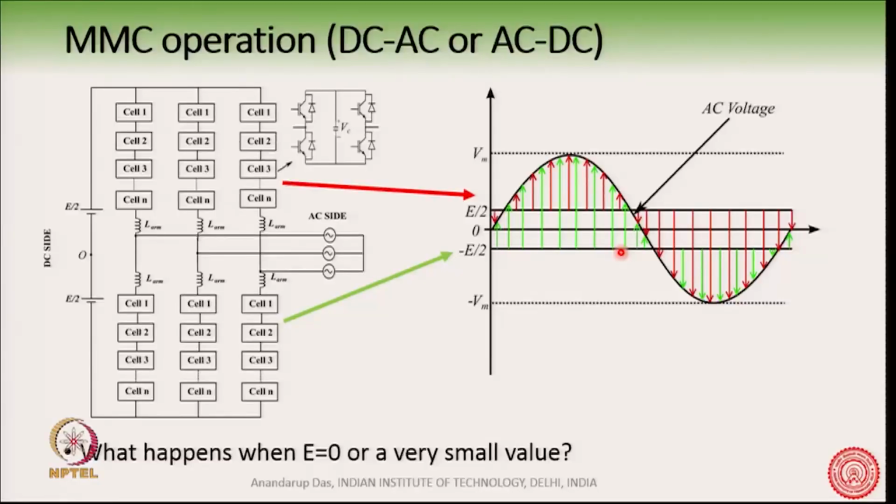The advantage is that this is a very severe fault, a pole to pole fault, but the short circuit condition can be tolerated at least for a certain duration of time. But we will definitely need the full bridge converter in order to have something like this.